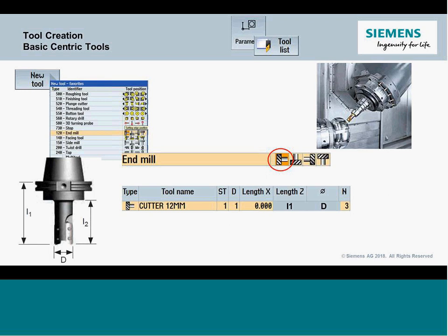And you don't actually even have to worry about gamma, right? The tool's spinning, so there's no worrying about orientating the live spindle portion of it. Drills, build all your end mills as if they're pointing toward headstock 0, and then let the system swing them around.